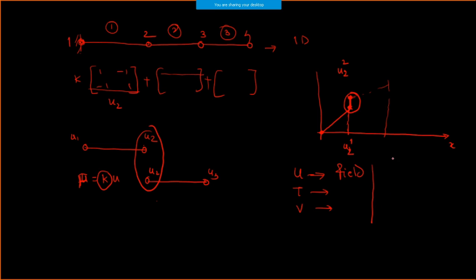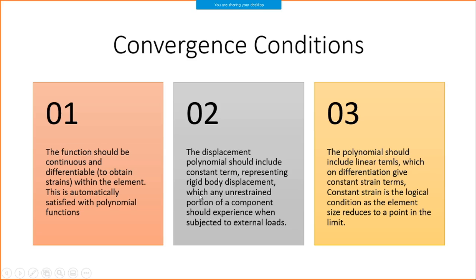The order of differentiation of this particular thing is 0. So I'm going to match the displacement of this U2 and this U2 at the particular node, and that's why it is called a zeroth order differential equation. That's what C0 is.